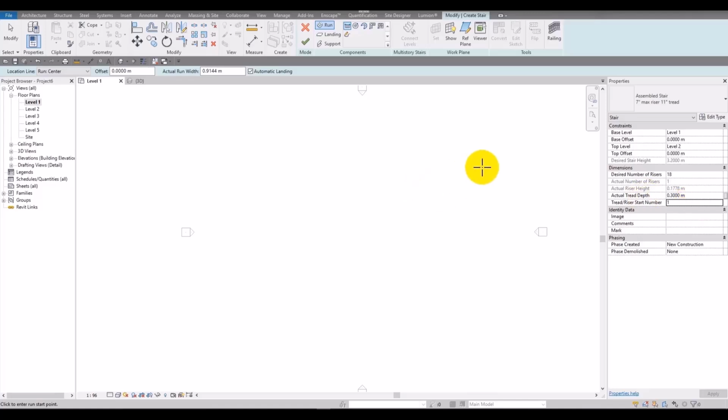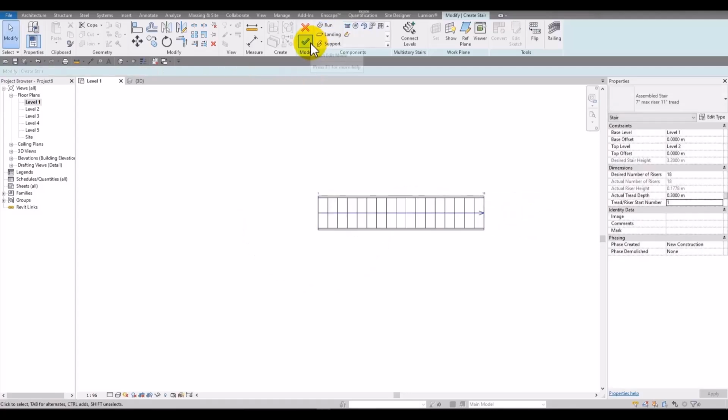When you control the number of stairs and steps here, and when you are in run, the first item here, when I draw it, it's a stair. I click here. As you can see below the mouse, I can see the number of risers which are created so far, and the remaining treads, 8. I complete them, and at the end I click, and here finish editing mode.